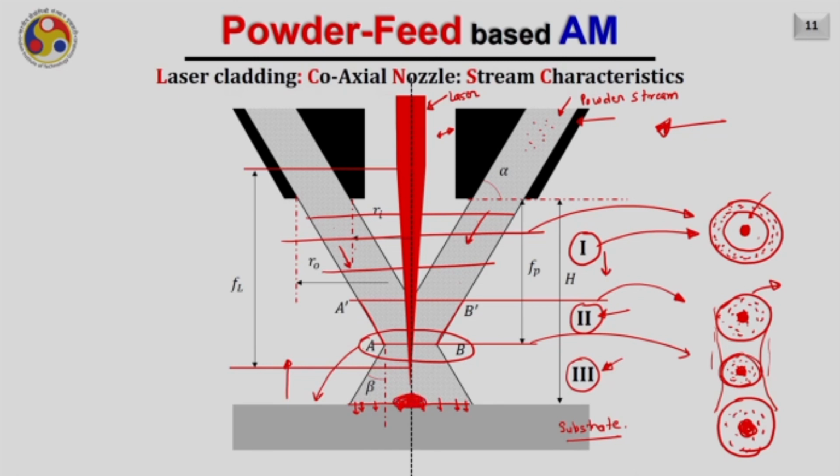So it is very essential for us to understand how much powder is going to be inserted and participate in creating the bead on the substrate. If we come to know how much this powder amount will be, then if we assume that the bead profile is parabolic, we can easily predict its height if the width is known.